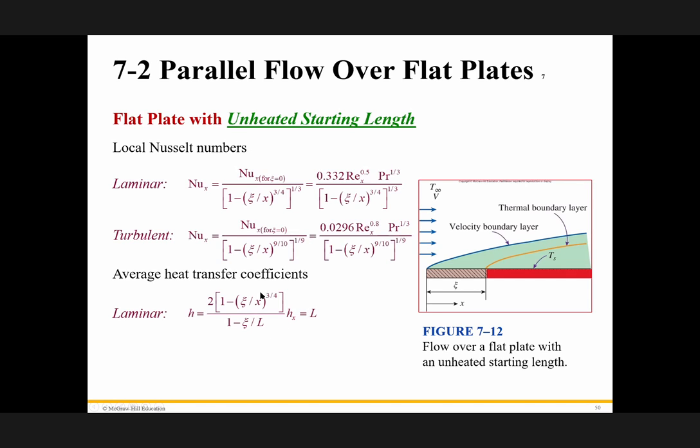And we put this equation to calculate the average heat transfer coefficient. Therefore, this is the hx we calculated at the end of the plate at this point. The problem asks us to calculate the heat transfer at this point. I know at this point, I'm trying to find the average from here to here. If you remember, the heat transfer coefficient drops exponentially right here.